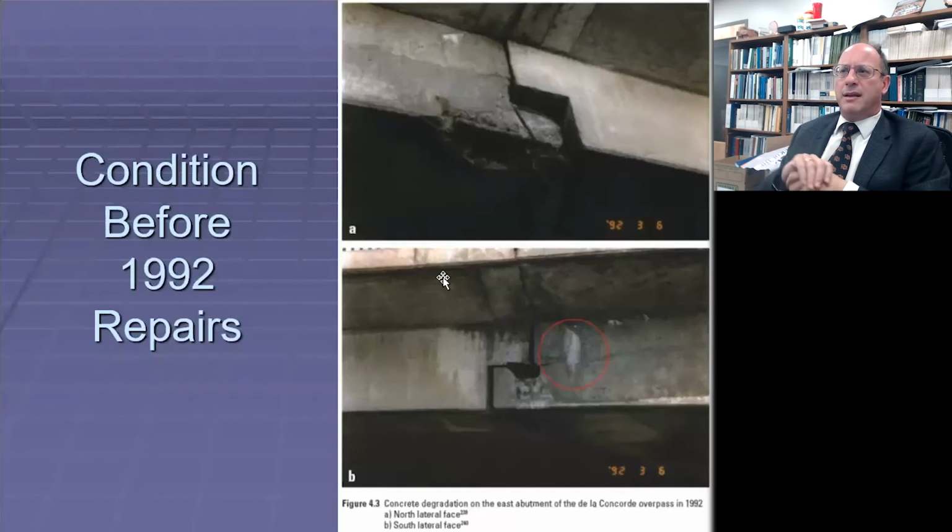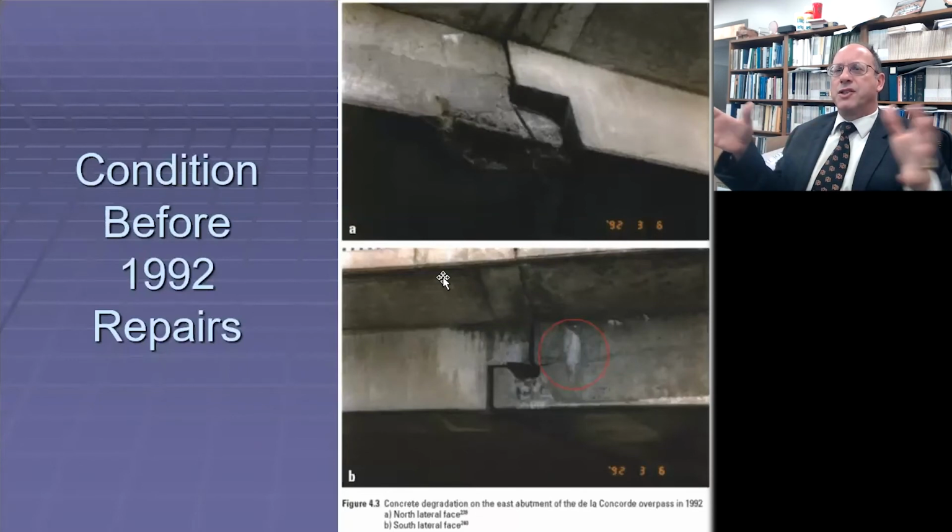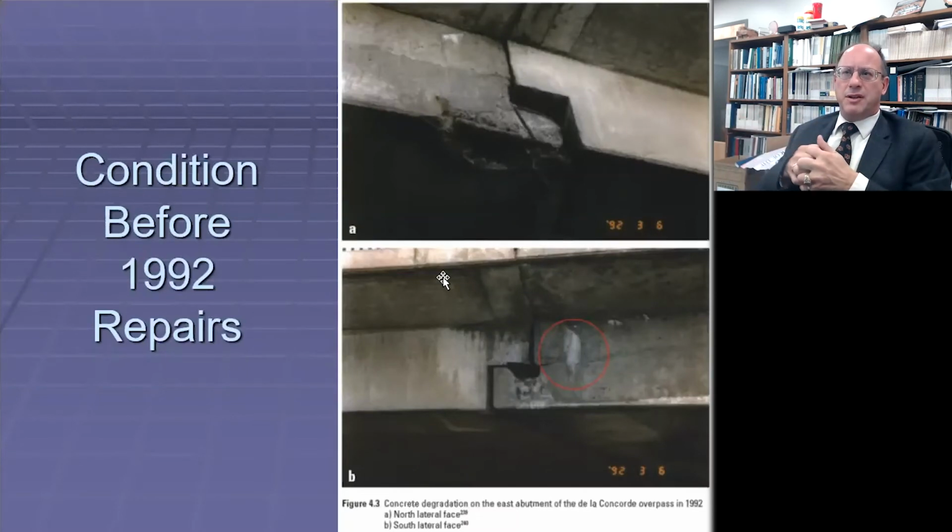All not looking extremely healthy. And not only does that have to support the vertical load of the end of the box beam, but as that expands and contracts, it's going to have a tendency to also apply some tension and some prying and to pull apart those. So clearly those supports are a point of weakness.